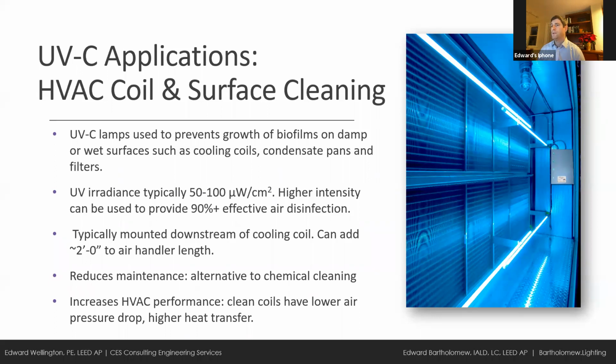The other major benefit of mounting UVC lamps in this orientation is it keeps your coils clean. So it reduces the costly effort of coil cleaning and reduces using those chemicals that lead to poor air quality and groundwater contamination.